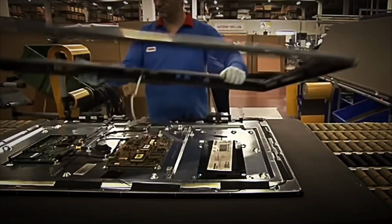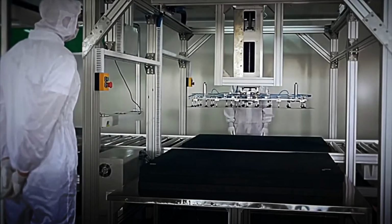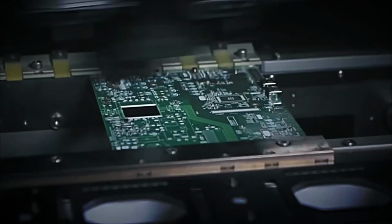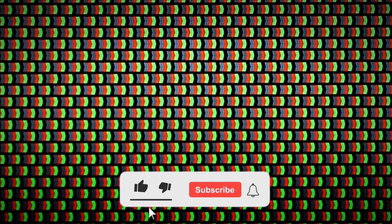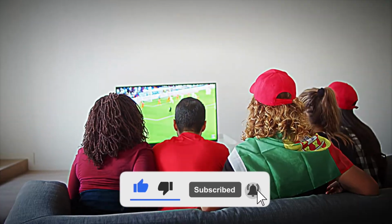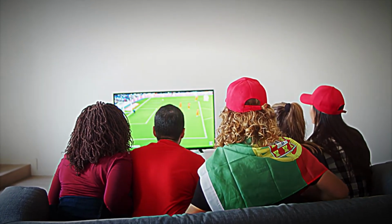But what is it that truly brings this screen to life? The answer lies in the insertion of a matrix of transistors, small electronic devices that act as switches for each pixel. These transistors meticulously control the brightness and color of each point, ensuring that the image is sharp, with astonishing details and true-to-life colors. And to achieve that infinite palette of hues, color filters, red, green, and blue, are applied, which when combined in various proportions, generate the incredible chromatic diversity we see in every scene.